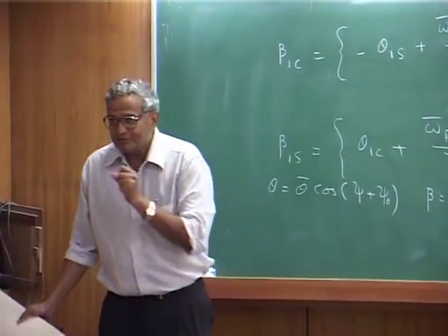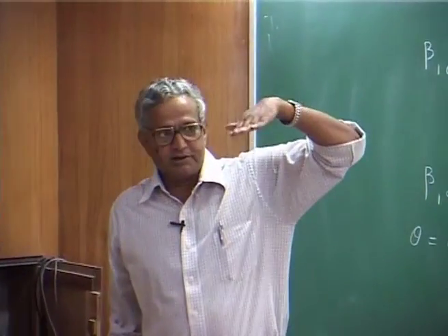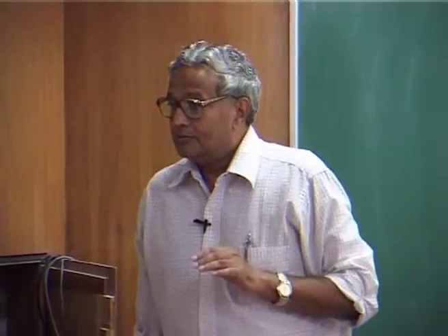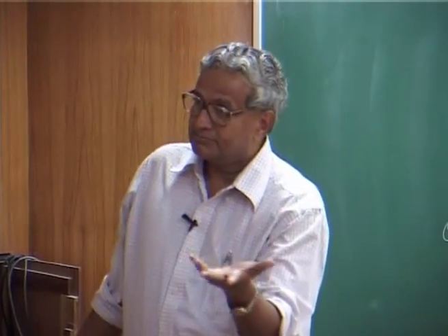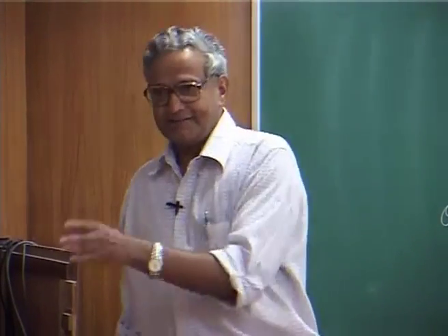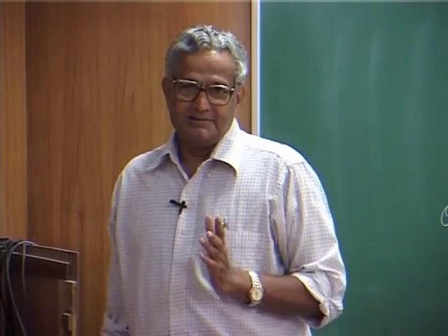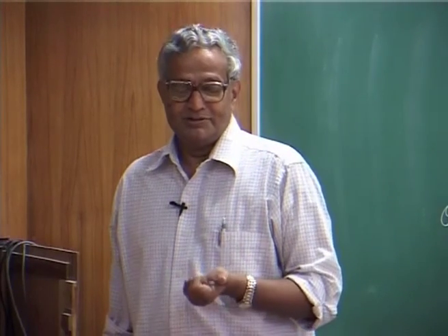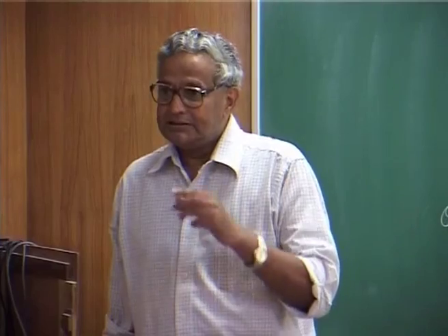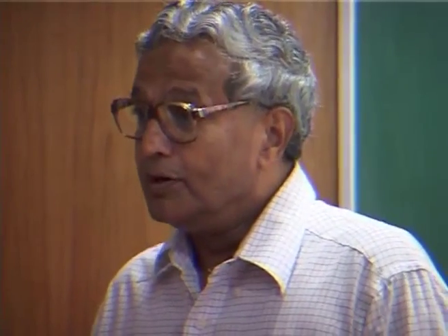We are looking at how the cyclic inputs affect my rotor tilt, but how much it affects, it is like this. If the pilot gives an input in the longitudinal direction, thinking that he is tilting the rotor disc like this, he wants to go forward, what he will do is he will also start rolling. Not only will he pitch, he will start rolling, he will start moving left or right depending on the coupling. So, that means the two axes are not independent, they are coupled, which is difficult to fly. When you really want to go in forward direction, you will start going in some other direction. If you want to give pitch, you will roll, but you will also pitch.